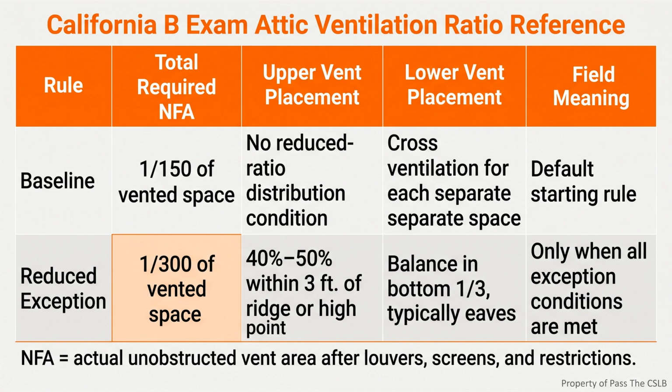The insulation crew pushes bats hard against the roof deck. The exterior vents remain visible, but the intake path is choked. Moisture that reaches the attic has less opportunity to be carried away, and the upper exhaust may begin pulling air through ceiling leaks instead of through the intended eave openings. The immediate problem is not that the roof lacks vent products. The problem is that the air route has been broken. Based on the published Contractors State License Board study outline, roof framing is testable material.